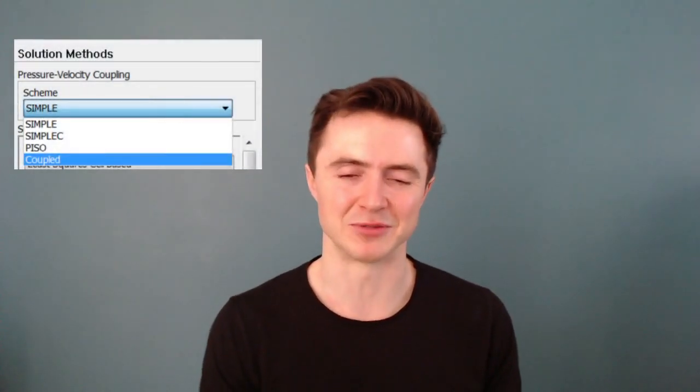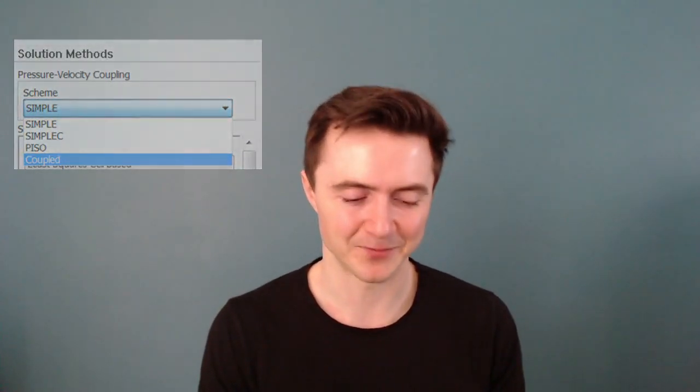There are some intricacies involved, and I really want to highlight these in this talk so that you have an even deeper understanding of how the pressure equation is included in the coupled algorithm. I'm also going to be wrapping up this talk by talking about some common recommendations for whether you should choose to use the coupled algorithm or whether you should just go with a standard segregated algorithm like the SIMPLE or PISO algorithms. They're going to follow at the end of this talk. All right, let's dive in and start by looking at how the pressure equation is incorporated into the coupled matrix algorithm.